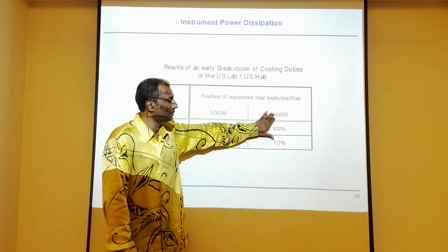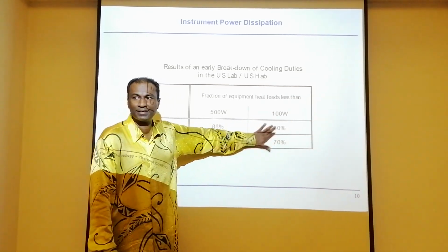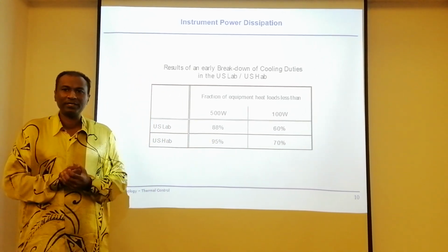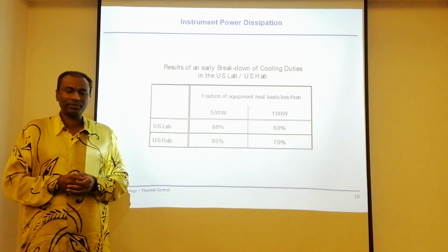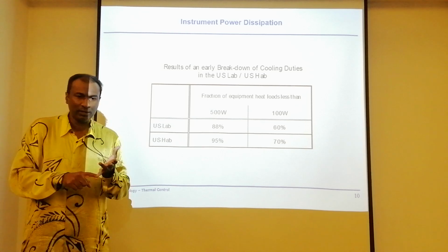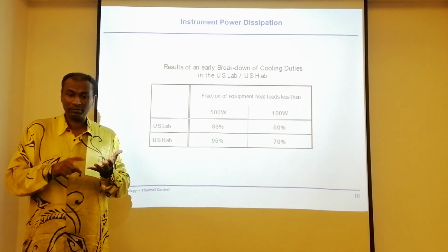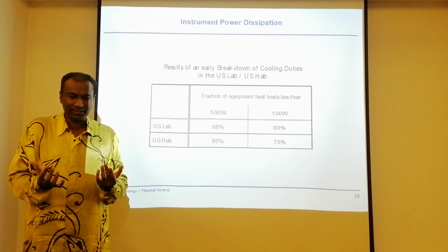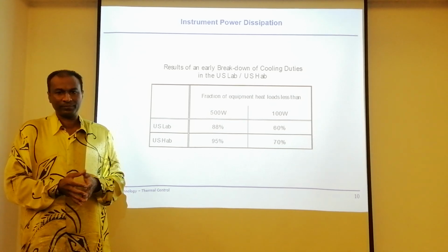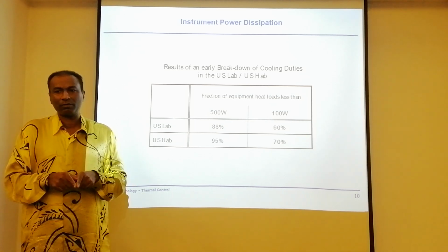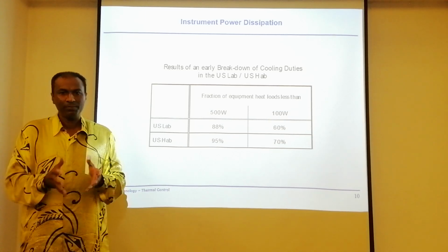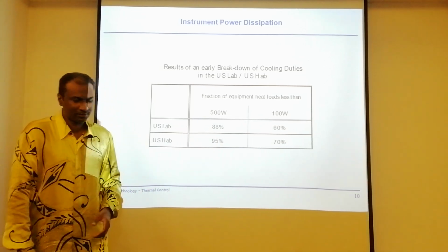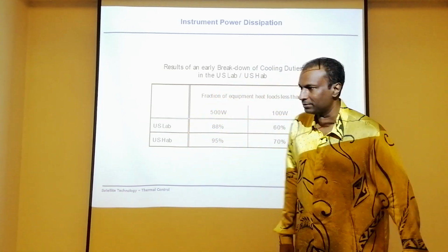So if you have low power consumption, you have less heat generation. So in a way, when you want to procure a satellite, you want to go for low power consumption. Therefore, it is going to be low power dissipation. So dissipation is low and you will not burden your thermal control system. That's important. But if you put a human on board, you can't run away. You'll fall in this category. You have a lot of equipment to maintain the human's comfort zone in space.